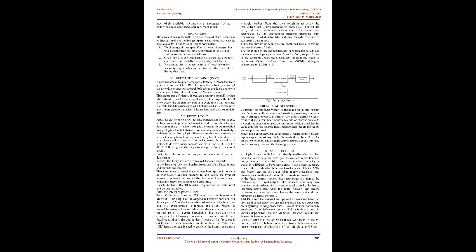Technique. Field of application. Advantages. Drawbacks. Discharge test. All battery systems. Easy and accurate, independent of SOH. Offline, time intensive, loss of energy. Open circuit voltage. Lead, lithium, Zn/Br and Va. Online, cheap. Low dynamic, error if acid stratification, sensitivity to temperature and sensor.